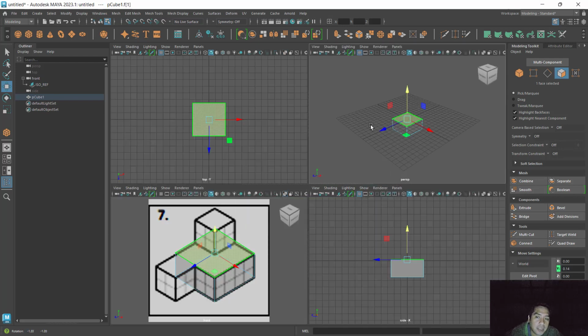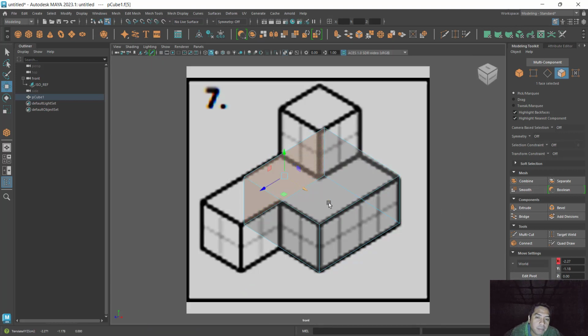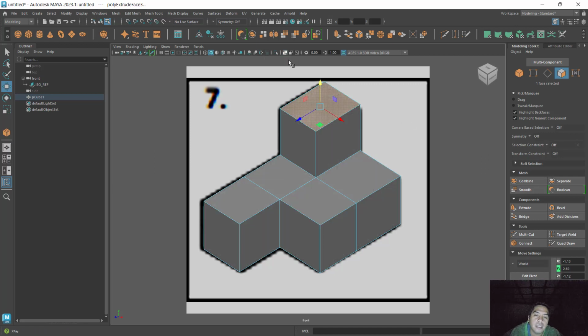And then I will push, as you can see, in the perspective. It's also a big help. Next is I can push this back further up to this portion, because now I'll do some extrusion, holding shift and drag. And then this I can shift and drag. And then this, I'll just do a connect, W, and then I can just move it a little bit. And then I can select that corner, shift and drag. And then that's it.